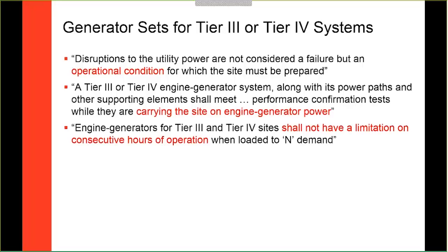So you can see here, if you look at these things and you look back at those ISO ratings that we talked about, you'd probably notice that the only rating that really makes any sense here is continuous operating power. It's the only rating that is set for 8,760 hours a year. It's set for continuous load at 100% load factor. The issue with that, as you can imagine, is it may drive towards a generator set solution that may be a bit oversized.